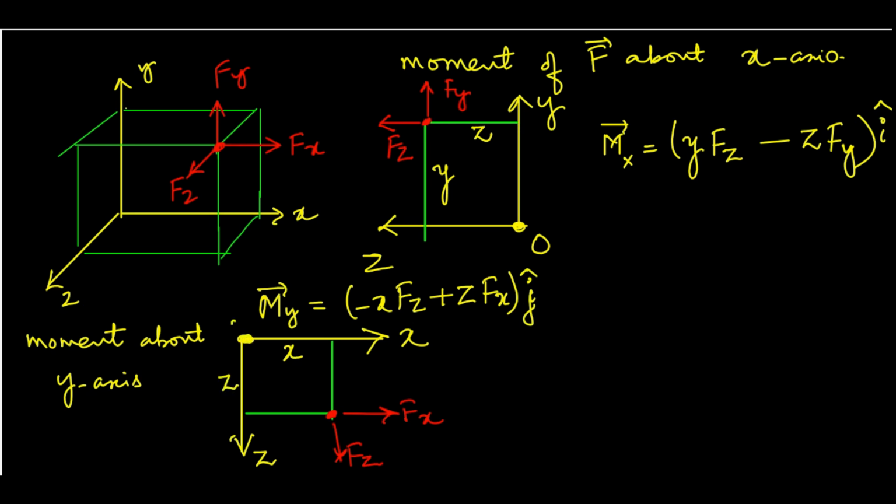So about your y-axis, which is now in this figure coming out of the plane of the paper, about the y-axis, your force Fz is causing a negative, clockwise moment and force Fx is causing a positive moment.